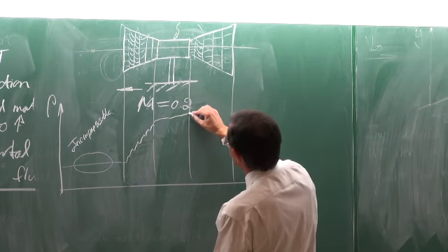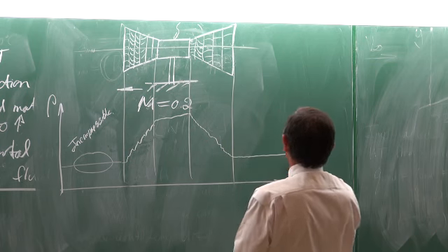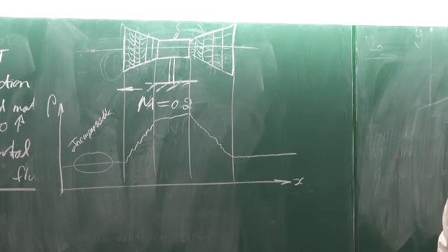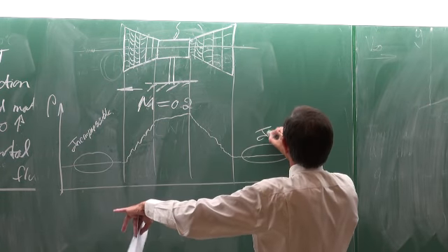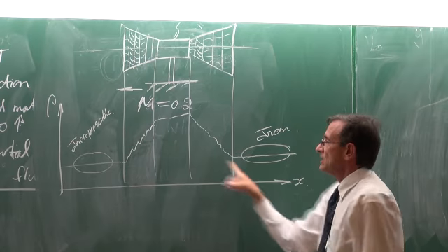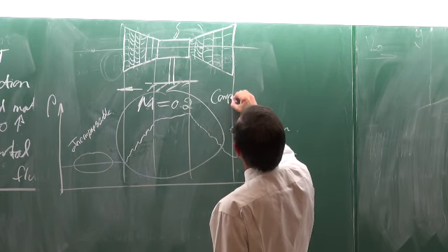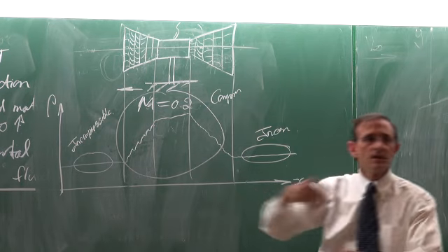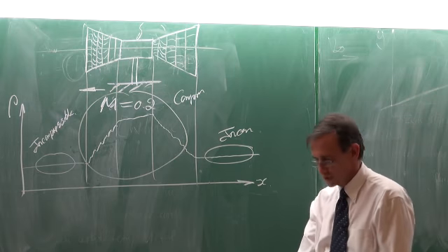And in the expansion process, it goes through the turbine, through all the different stages, and then it will go out like that again. So there it's incompressible, and there it is incompressible. In this region here, it is compressible. For obvious reasons, we can see the density is changing as a function of position. Do you agree?